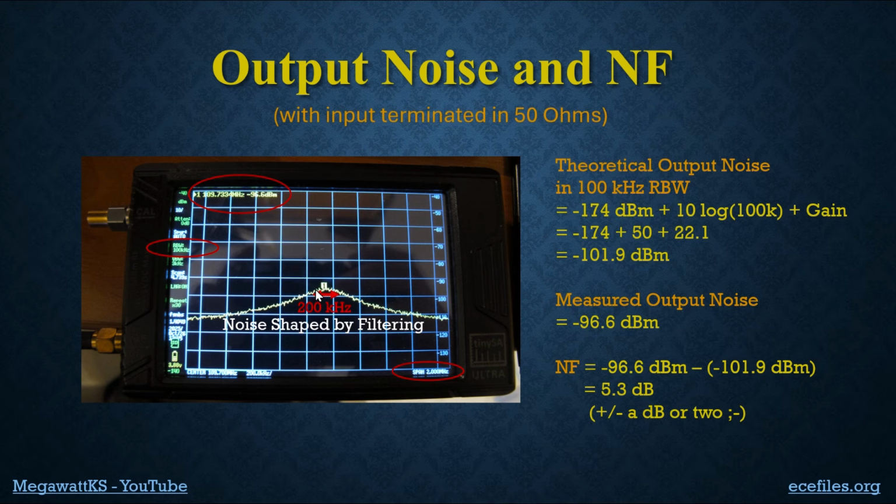That noise that comes out should be shaped by the transfer function or the frequency response of the Q-enhanced LNA filtering. And in fact, here it is. It's about 200 kilohertz wide, which is what we expect. The span, this says 2 megahertz, so the span is 2 megahertz, so each division here is 200 kilohertz. The resolution bandwidth that I'm using is 100 kilohertz. It needs to be less than what you're measuring for the bandwidth of the noise, so that's less. This may have a little of impact, but not enough for me to worry about.